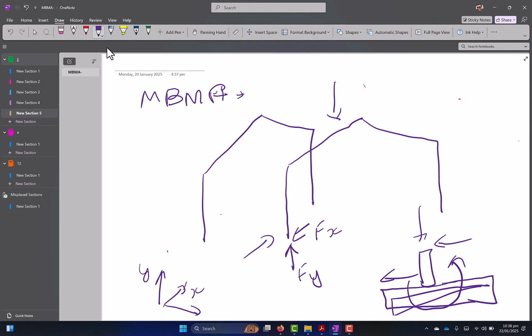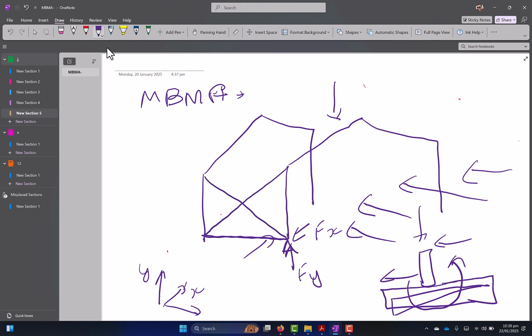That's it. There is no need of plinth beam because there is no force in this direction. Since this is a pin connection, if there is a force in the z direction, or what we call an orthogonal force, that is resisted by the cross bracing. In case this is the eaves truss, this becomes the compression flange, and if this is going like this, this becomes the tension member. So the tension is created here, compression is here, and this takes the load in the other direction.